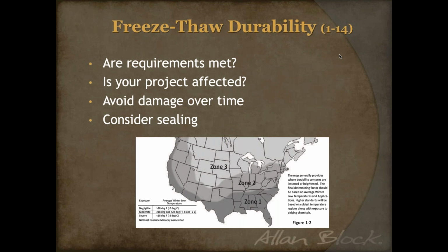Really, on top of any concrete product, as you all know, de-icing salt can very slowly degrade any concrete product. So we try to say keep it away from the face of the wall and the top of the wall. You can use a stone cap as a divider for any steps or walkways to keep that de-icing salt off the wall.